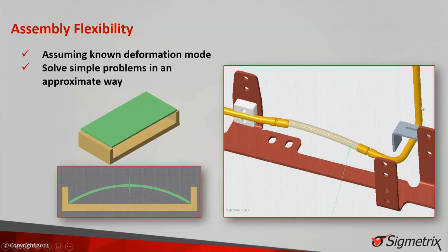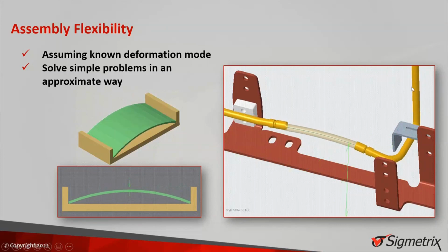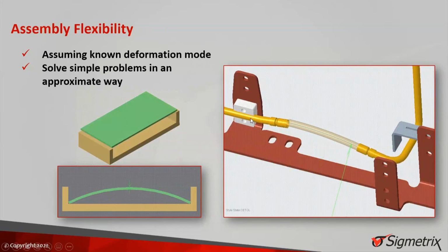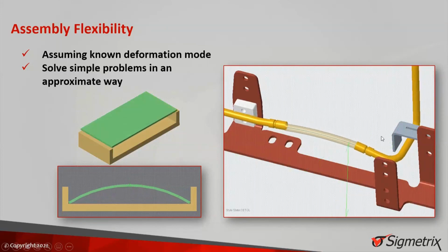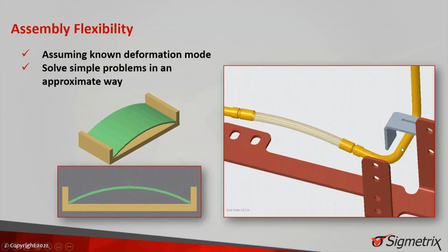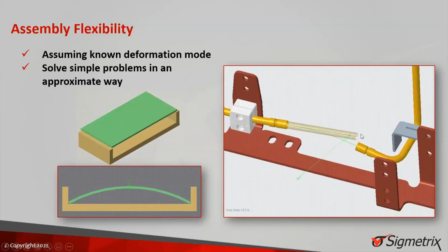And also, this is a pipe, right? There are two rigid pipes, and also there is a flexible hose between them, and you try to measure some clearance somewhere. On your detail drawing, you always make the dimension, for example, the length for the flexible hose.